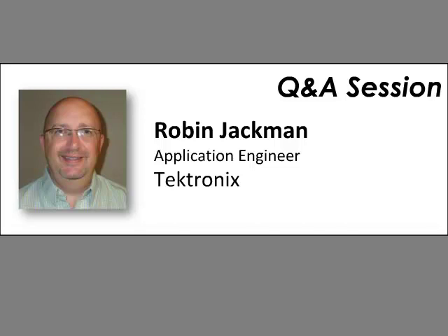Wow, okay. That's impressive. Our next question is, are Tektronix MDOs immune to compression effects from different frequencies? No. There are compression effects in almost all instruments. The Tektronix MDO4000 is what I call an entry-level to mid-level spectrum analyzer. It has a different design than a swept-tuned or a real-time signal analyzer.